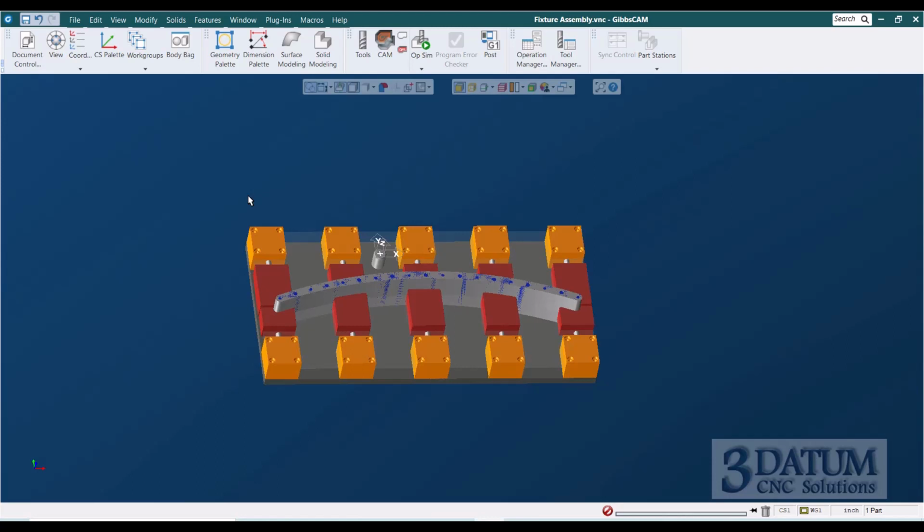If you take your finished part, any fixturing you have, or anything that you need from op one that you need to carry over to op two, build a coordinate system on your part oriented the way that it's going to be oriented in step two, and then do the coordinate system bouncing, and everything, including your facet body, will go with the rest of the assembly or the rest of your parts to align to coordinate system one.